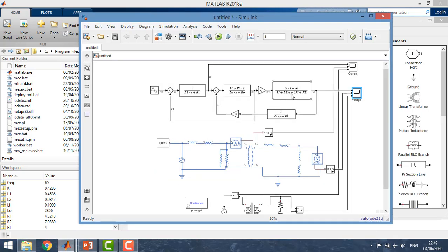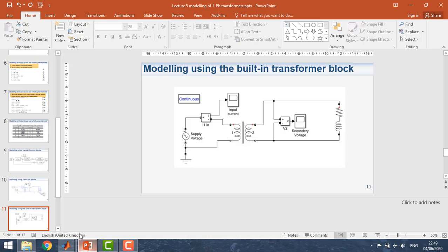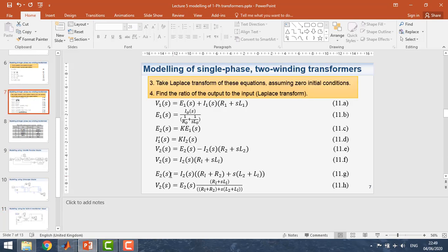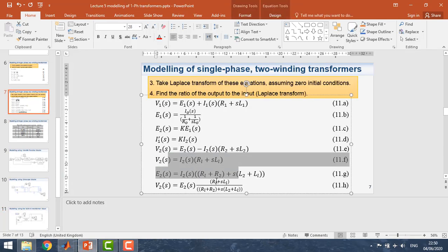One remark for the first model is that building the model in this way, we can find the secondary winding current in terms of the induced EMF in the secondary winding, and then find the voltage of the secondary windings using these two equations. In this case we have to use the derivative block, and I've seen a lot of discussion trying to avoid using derivative blocks.